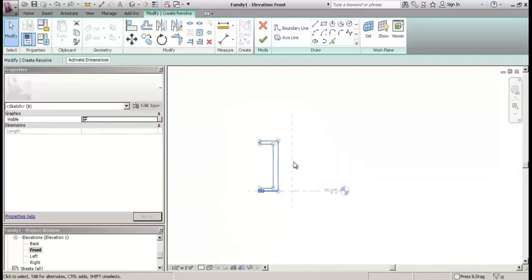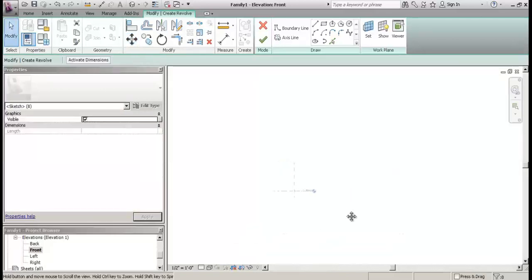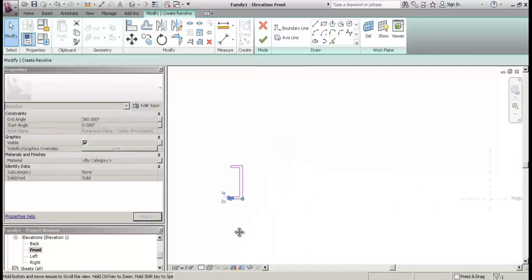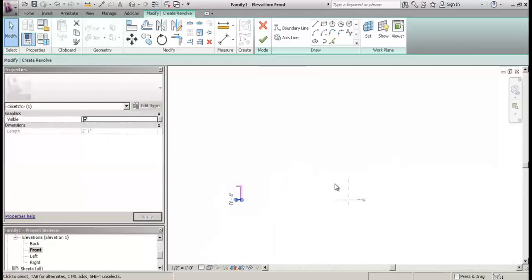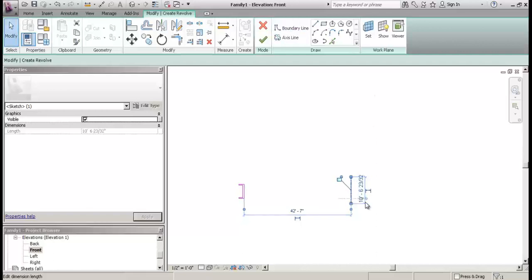And you know, I'm going to go ahead and move this. I'm going to make it really far out there. And we're going to use the center line of our reference planes to actually make a curved piece of geometry, or curved extrusion for that matter. So in Rhino, this would be like your sweep along a path kind of thing. If you're doing a revolve, or you can do the revolve the same way. So what I'll do now is I'll do my axis line, and I'll pick my axis line based on my reference plane. I could also draw it in, but I think knowing how to do the reference plane by picking something helps a lot with understanding how we set up geometry later on when we do parameters.